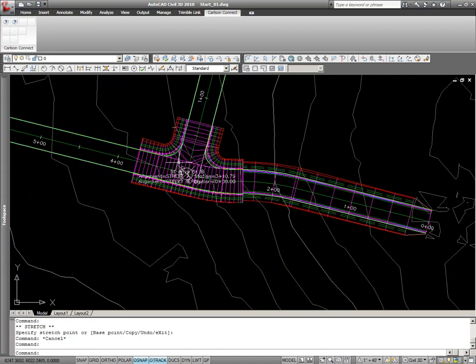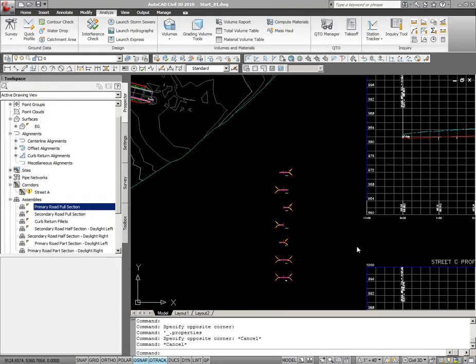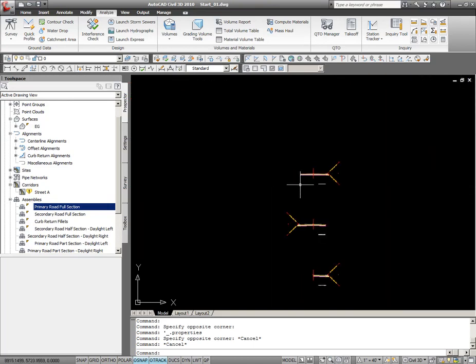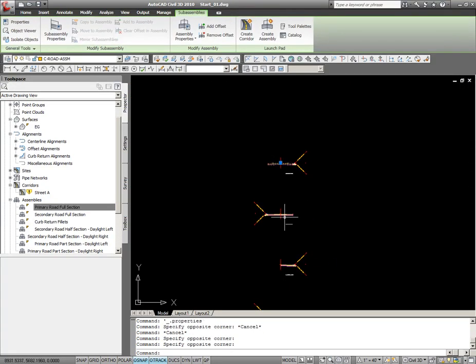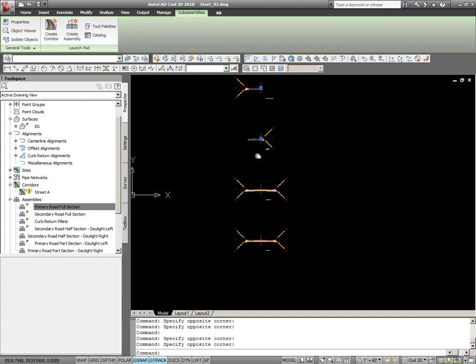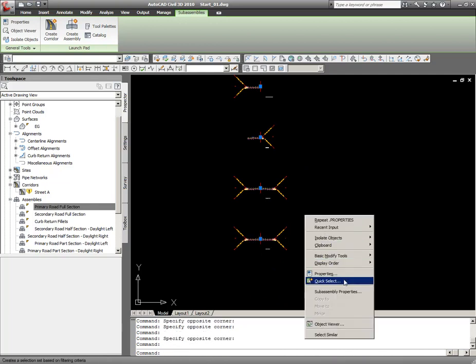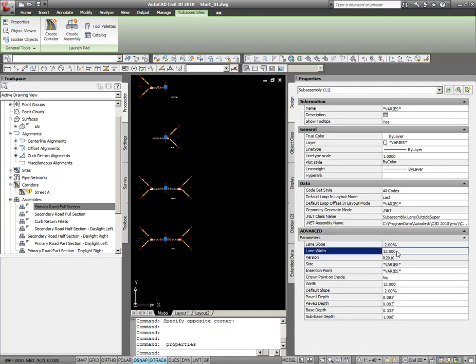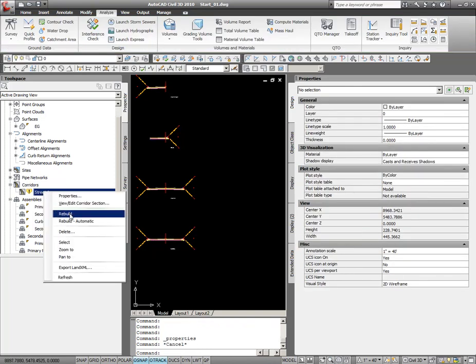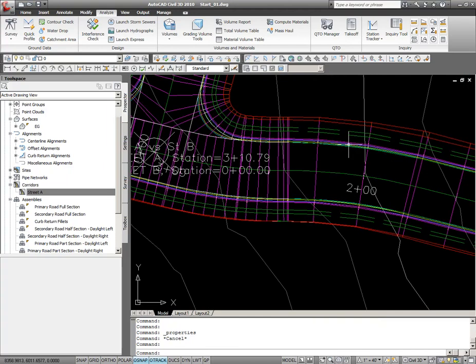You'll notice a little bit of offset, 12 foot versus 15. I set up a 15-foot lane for my intersection, but all my subassemblies over here have a default 12-foot lane. And that's relatively easy to fix by simply selecting all my lane subassemblies and adjusting their default lane width to 15. Now when I rebuild the street, I'll see that the lanes match up.